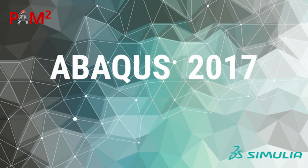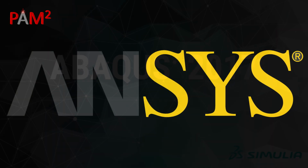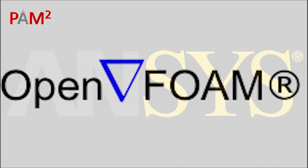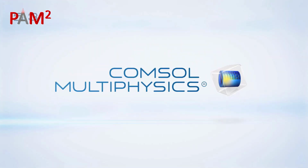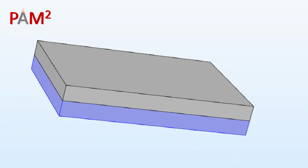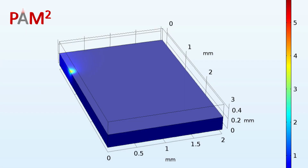There are several software packages that can be used for SLM modeling, like COMSOL, Abaqus, and ANSYS, which are based on finite element, and ANSYS Fluent and OpenFOAM, which are based on the finite volume method. COMSOL is a powerful software which can take care of thermomechanical modeling of SLM. In this case, the thermal field is basically the driving force for the mechanical model. In this video, we are going to show you how easily you can implement COMSOL for thermal modeling of SLM, which is the main cause of deformations and microstructural evolution.